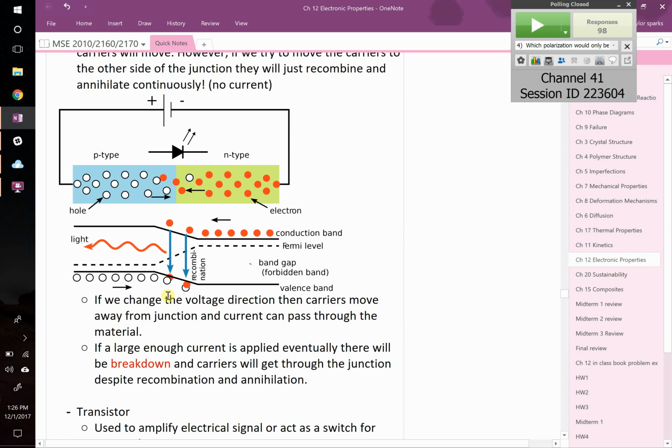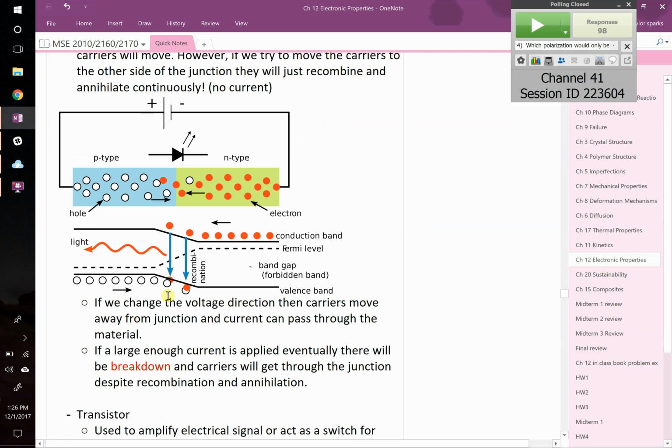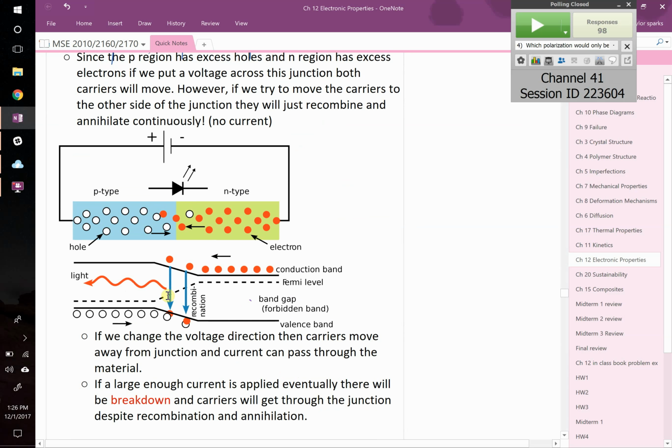Okay. So again, this is another diagram of exactly what I just said. Another way of drawing these band diagrams is to say that the Fermi level moves if you dope it p-type or n-type. This material, the dashed line, is the Fermi level. Again, that's where the electrons would like to sit at, but it's above their valence band. This one, the Fermi level, is closer to the conduction band. Therefore, this thing has lots of holes, and this thing has lots of electrons.